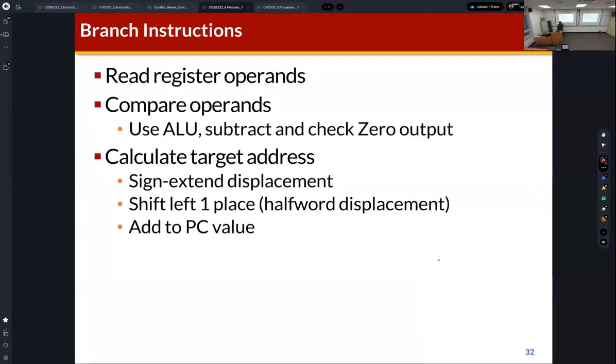Then we need to support the branch instruction. So this is the behavior of a branch instruction. The first, like BEQ, RS1, RS2, and target. Target is actually an immediate number. It's immediate 12 down to 1. Okay, this is the behavior of the branch instruction.